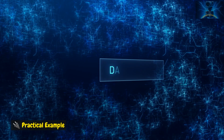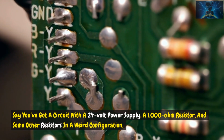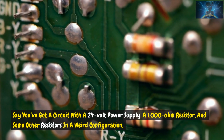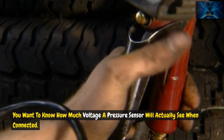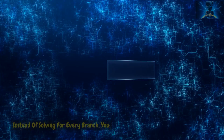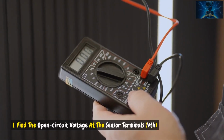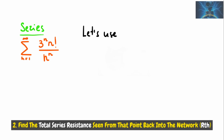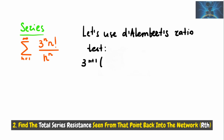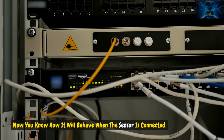Practical example: say you've got a circuit with a 24-volt power supply, a 1000 ohm resistor, and some other resistors in a weird configuration. You want to know how much voltage a pressure sensor will actually see when connected. Instead of solving for every branch, you 1. Find the open circuit voltage at the sensor terminals, VTH. 2. Find the total series resistance seen from that point back into the network, RTH. 3. Done. Now you know how it will behave when the sensor is connected.